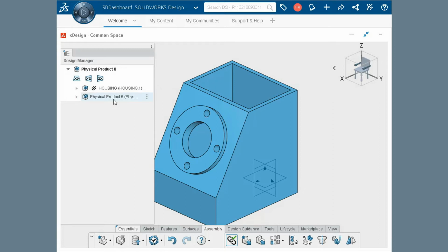The active assembly I mentioned in the last step is defined as the one that is currently being edited, or the one in focus. Now, by default, it's the component that was created to start this lesson. Another way to describe it is as the top level component in the tree, the main assembly. In order to work on the new component, I'll need to activate that component. The procedure is very direct. Just double-click the component in the Design Manager.